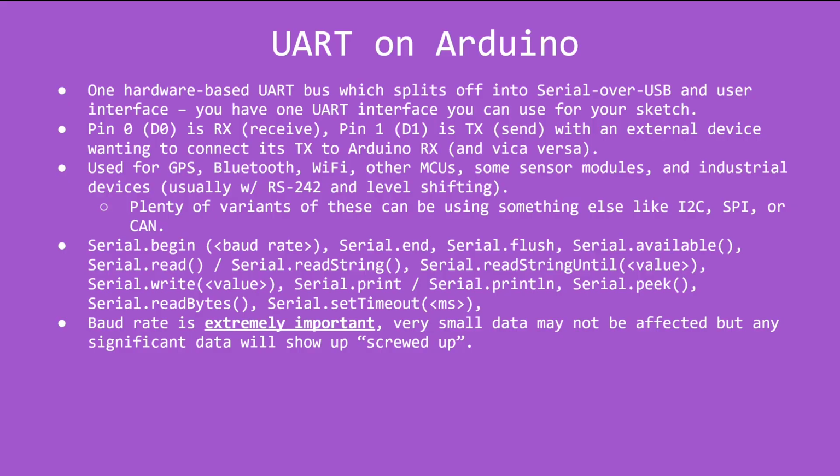Always keep in mind the most important thing is baud rate. It's got to match. Some really small data might not be affected, and that might give you a false positive, but anything more than that, it will show really screwed up, just like random characters.